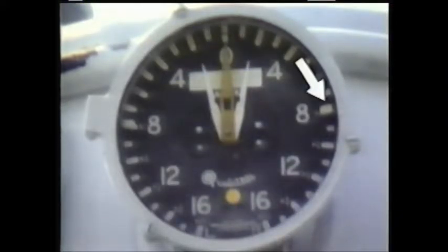The numbers to the right of the 0 indicate the position of the tap changing mechanism when the value of the load voltage is being increased over the value of the line voltage applied to the regulator. The numbers to the left of the 0 indicate the position of the tap changing mechanism when the value of the load voltage is being decreased from the value of the line voltage being applied.